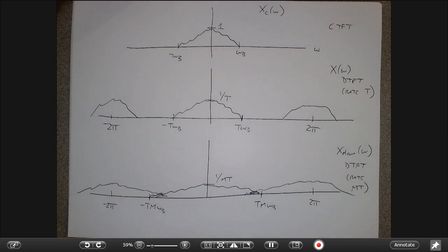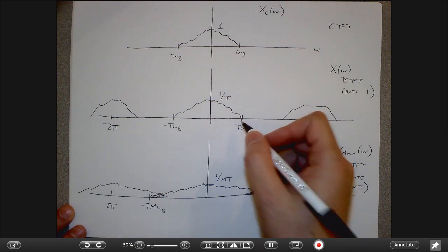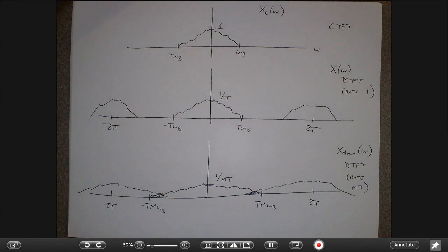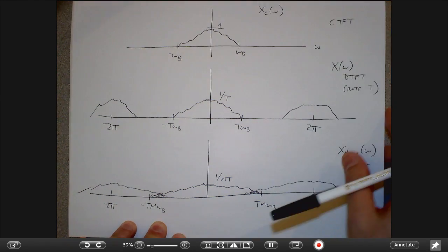And certainly, if I'm sampling less often, my Fourier transforms have a much higher probability of aliasing, right? And so the only way that I can downsample the original discrete-time signal without getting aliasing is if I happen to have sampled that signal very fast to begin with, right? Because the effect of downsampling is to spread out these copies even more in the frequency domain. So aliasing can definitely occur.